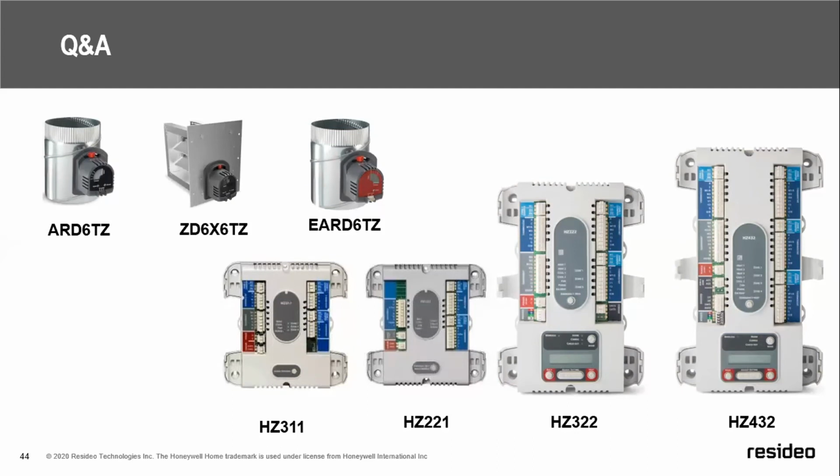And so I often have folks say, well, help me visualize where that would come in handy. Well, let's pretend that at the top of the stairs in a 2-story house, nobody sleeps in the hall where the thermostat is. So you've got the ability to go ahead and put the RedLINK sensor in the master bedroom and the kids' bedroom, and everybody can close their door for privacy and have perfect temperature control in the bedrooms where it's not paying necessarily any attention whatsoever to the temperature in the hall where nobody's sleeping.